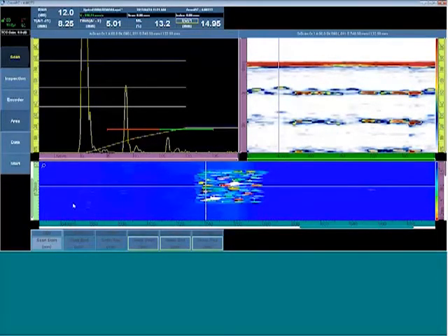The software will not allow you to configure a C-scan that exceeds the capacity of the instrument to save the data file. For most MX2s, that's 300 megabytes. For most MXU first generation OmniScan, that was 160 megabytes.